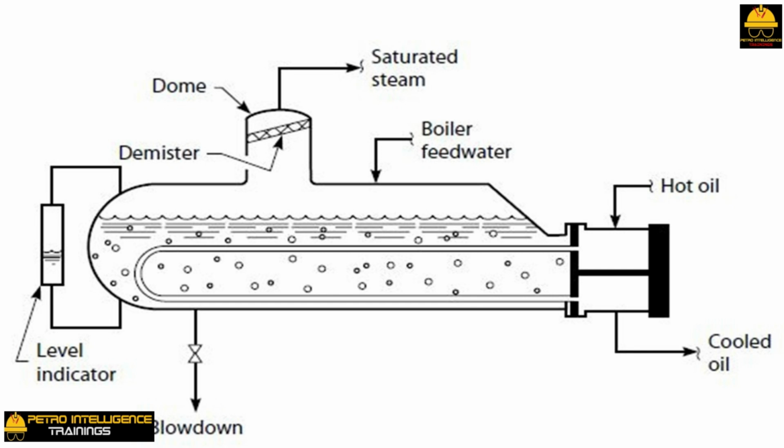Why? Well, because the water inside the kettle is boiling water. The water density has been reduced by the bubbles of steam. I have discussed this problem in detail in my video on level control. Basically, the difficulty is that the water in the level indicator has a specific gravity of about 1.0. The boiling water in the kettle has a specific gravity of perhaps 0.5. If we have 4 feet of boiling water in the kettle, then, by pressure balance, we will have 2 feet of cool water in the level indicator.